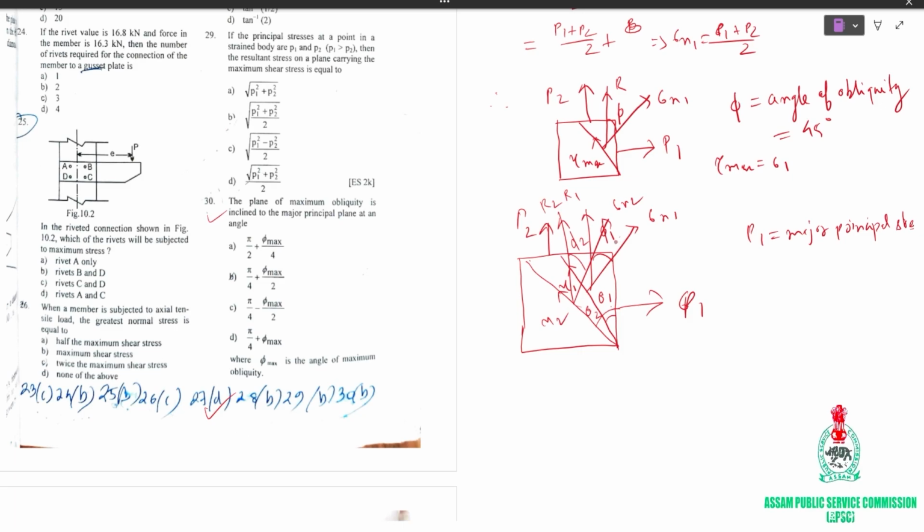So we have to find that phi where phi becomes maximum. And after we reach the maximum value, we have to find the theta value in terms of this maximum phi value. And that theta gives what value? Theta is pi by 4 plus phi max by 2.